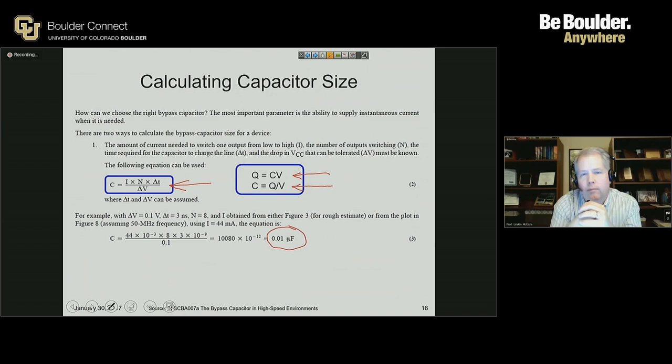Because you're trying to have margin. Capacitances have tolerance. Capacitors and other components have tolerances associated with them, and they change characteristics because of temperature, and they change characteristics because of aging, and you want to make sure that you've designed in to accommodate this margin.